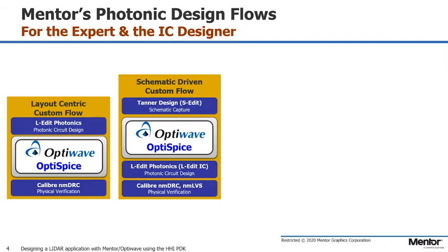Some of our users are moving to where they want to use a schematic-driven approach. Basically, they want to quickly realize their circuits in a schematic without having to have all the detailed waveguide routing, and be able to simulate and verify that the design is working correctly before starting layout. So you start with your schematic here, you drive directly into OptiSPICE, verify that the design is going to execute at the design parameters you need, and then you start LEdit Photonics and basically run the schematic-driven layout flow. Finalize your layout in LEdit Photonics, run DRC, and in some cases, some of our customers are starting to use LVS to verify that the schematic and the layout match, and then verify everything with OptiSPICE.